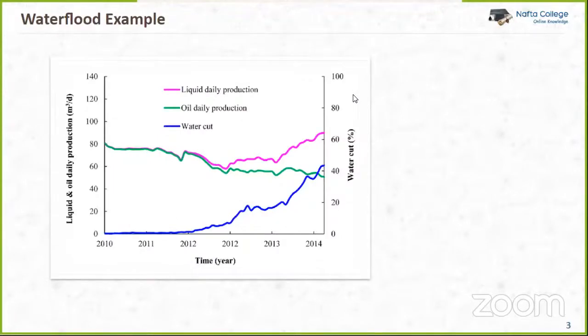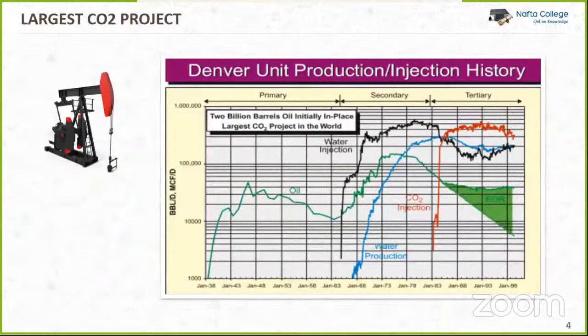And a typical picture, this is not the same field, but this is trying to illustrate that at some point in time, when the water injection starts really getting poor returns or diminishing returns, you inject more water, you will produce more fluid, and the oil keeps going down. And it's just like an automatic washing machine. And this is a typical problem, whether it's a green field or a mature field, and not knowing the parameters that you're playing with and the data, and the lack of immediate feedback will put you always trying to catch up with these problems.